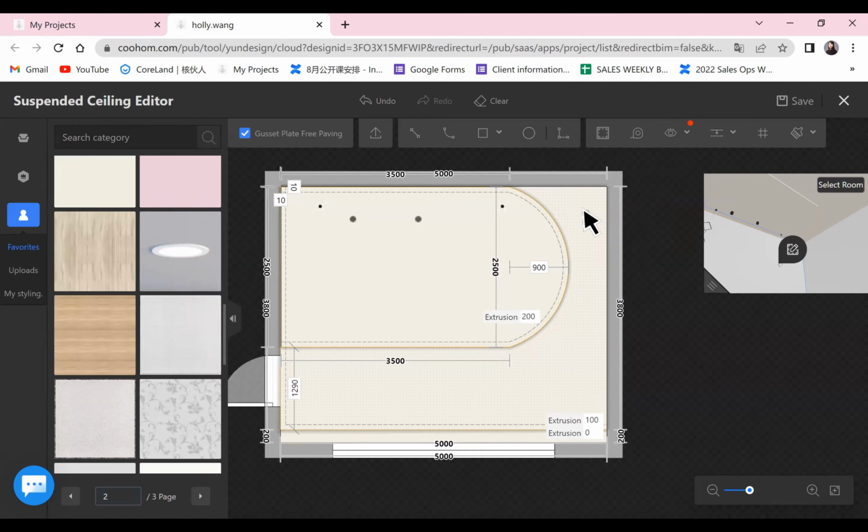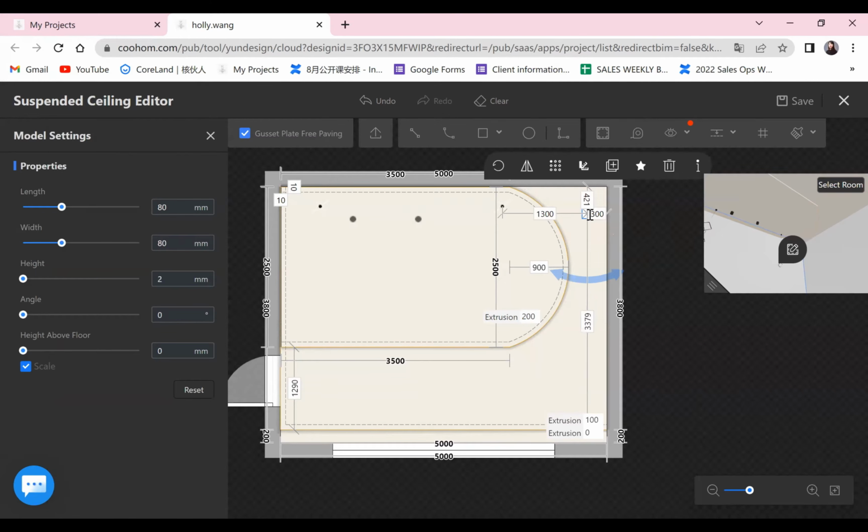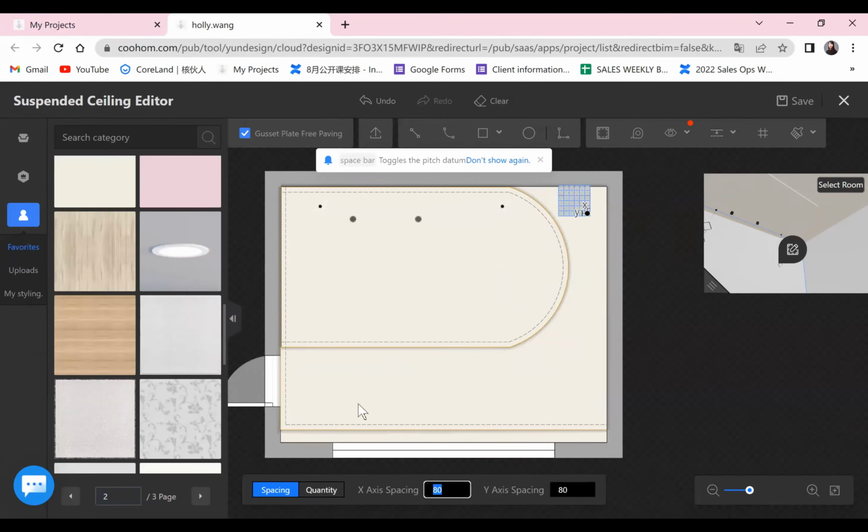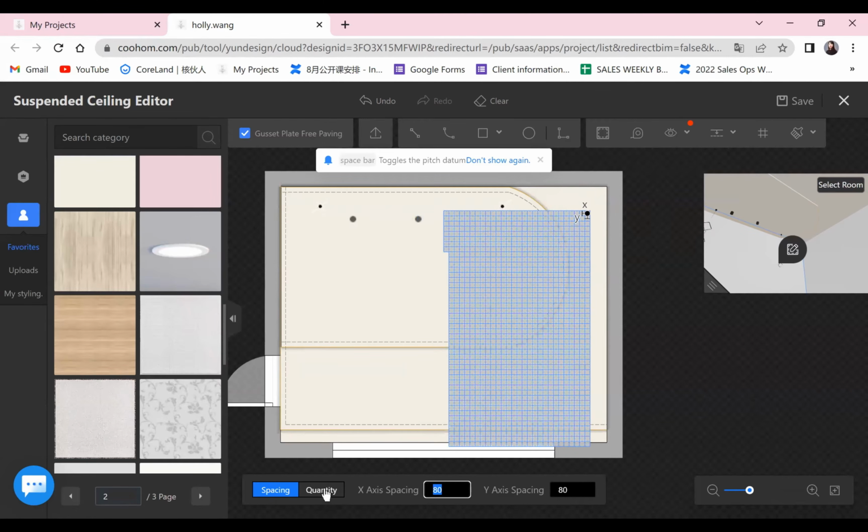to place the downlights. So when you click on it, you can choose array, and here they will get you how you want to place the lights for the spacing. For the X axle, we don't need it. For the Y axle, you can set spacing for each of them. Let's get a 1450.